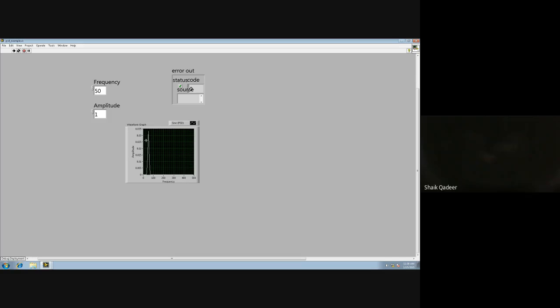The significance of PSD is that we can see which frequency content is dominant in our information. The power of that particular information with respect to the frequency can be seen. So I just vary this frequency from 50 hertz to 100 hertz. I'm changing. Accordingly, you see the pulse is getting shifted. What are you able to observe from this graph? At 100 hertz, you see a spike is coming, right?